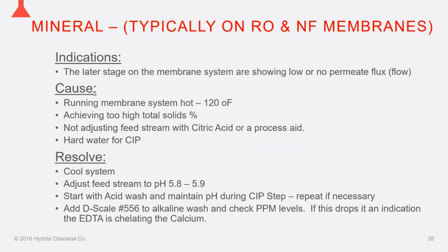I just wanted to mention one thing. As you stated before, the normal dairy soils that we'll expect will be phosphate and calcium scales, phosphates or carbonates that are readily soluble in acid normally. So where the EDTA comes in is if you have mineral soils, perhaps from a poor quality water supply, or something unexpected that isn't soluble at the regular acid pHs.